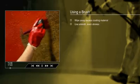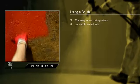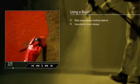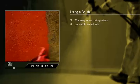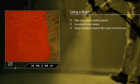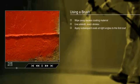The brush is used to flow the coating on the surface in smooth, even strokes, without undue pressure that could leave streaks or valleys in the coating on the surface. Subsequent application should be made at right angles to the previous coat in a cross-hatch style. This procedure helps ensure complete, even coverage and helps seal any pinholes from the previous coat.